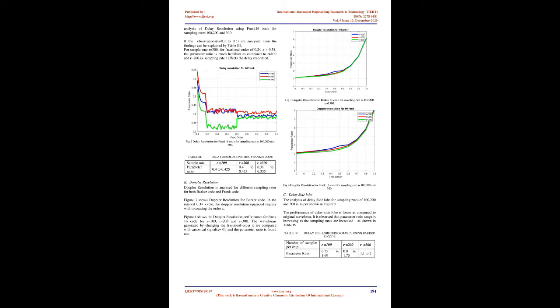Ambiguity function. To demonstrate the effectiveness of generated waveforms, ambiguity analysis is done. The ambiguity function represents the time response matched to a given finite energy signal when the signal is received with a delay t and a Doppler shift fd relative to nominal values expected by the filter. For a radar waveform w(t), the AF of a waveform in the libraries is outlined as follows. w(t) represents pulses transmitted and received. The AF shows the range resolution, the range SLL, the Doppler resolution, the Doppler SLL, and the spacing of the Doppler ambiguities. AF is a kind of math tool to study and evaluate the waveform performance effectively as it provides detailed information about the waveform.